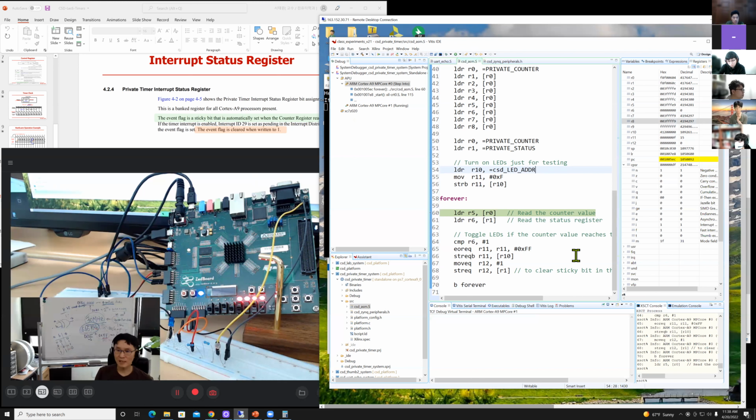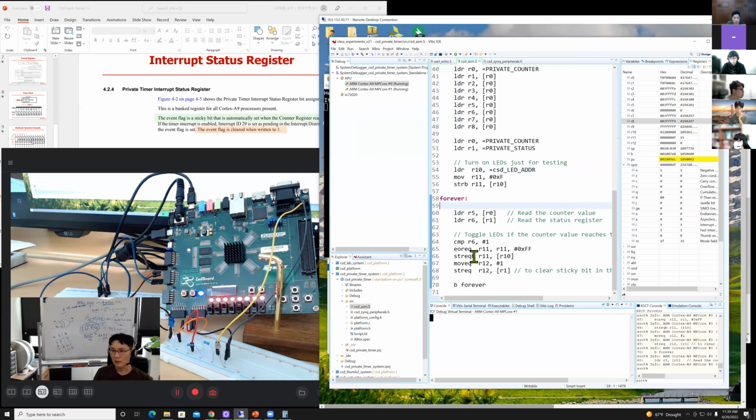Then in 1 second, roughly 8 countdowns. So that will toggle very fast, right? 8 toggles in 1 second, I think. Let me press F8. Right. Roughly 8. I don't know, roughly. Right. So again, polling method, because we are checking this one. This is polling, right? It keeps reading the status register to check that countdown. Okay.